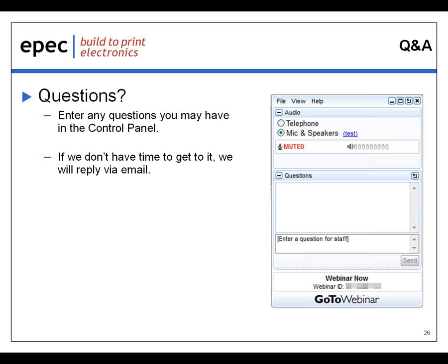Now, part of the polyester sheet is screened conductors that form the tail, and that can be terminated with either a crimp connector or a ZIF connector. The screened polymer conductors are very, very thin. They're typically 0.5 mil to 1 mil thick and need to be flexible so they can bend with the polyester. Taken together, the screened silver polymer conductors and the thin polyester assembly are fairly fragile and prone to stress fractures at the stress points, particularly in the flex tail area and the connector termination area.